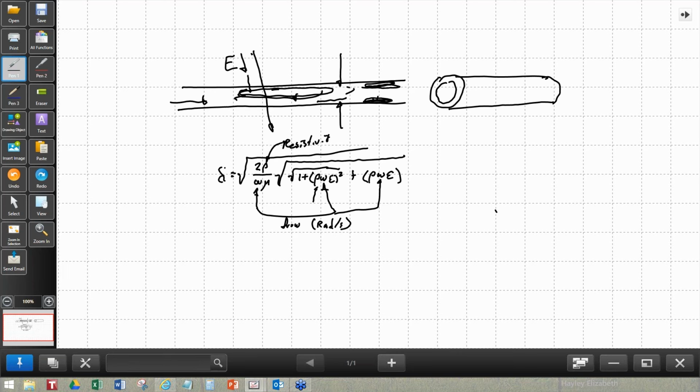Key thing to see is that instead of just having a normal type of equation, we now have these other factors that fall off and create an ability to squish it down to where we only have a narrow ring of conduction. Now this will happen in vias when you're carrying very, very high speed signals. Note that at terabit type signal rates, the actual skin depth may be less than the surface roughness of the barrel of the hole.